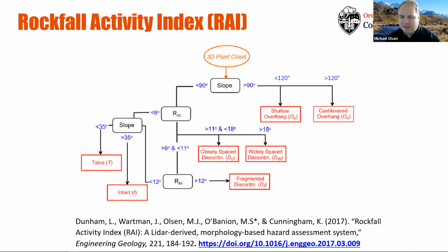The idea behind this approach is we compute morphological characteristics. So we look at a very localized slope vector, and we also look at roughness across different window sizes or different spatial scales, because that gives us information about what's present in terms of the rock and how the weathering processes are happening. Those are all indicative of roughness or rugosity in the surface of the slope.